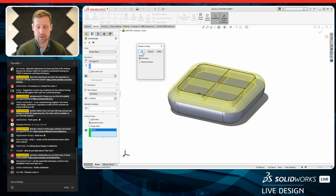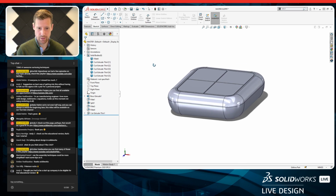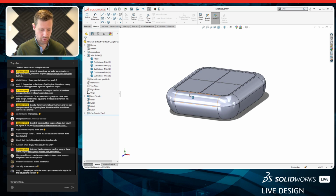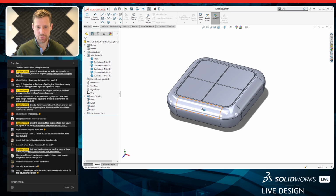As soon as I do that, it recognizes that I'm making cuts between bodies. It's making several different bodies. So it's going to ask me, do I want to keep these bodies? I'll say OK for all bodies. And there we go. So now I have several solid bodies, and you'll notice that it didn't cut through the bottom, it only cut through the top. So that's good. Now let's take a look at my solid bodies folder.